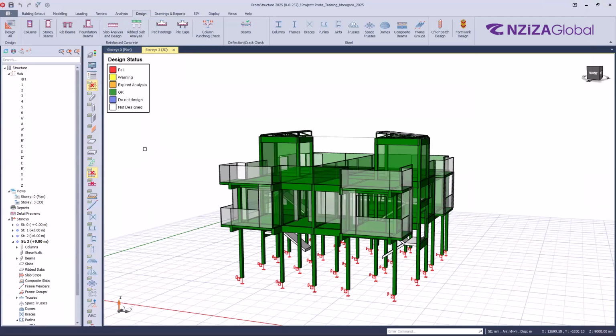Then you may put your drawings on a sheet which has a title block, and in the title block there is information you have to fill: the project name and so on. Instead of doing it manually on each and every sheet, you can fill in the information in the software here. Then there will be a field in the title block automatically, even in the report.